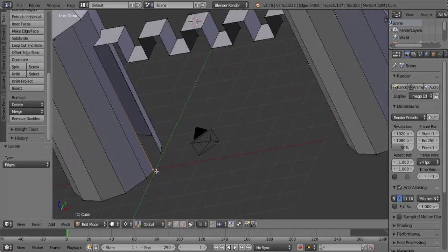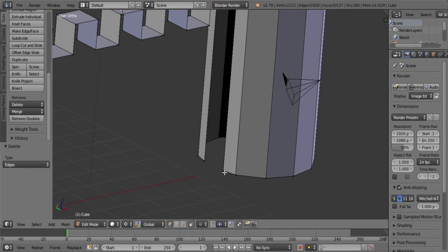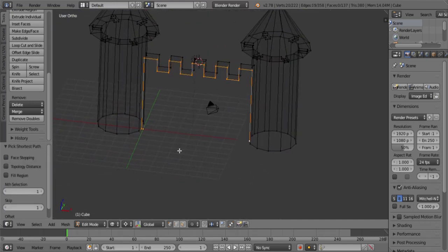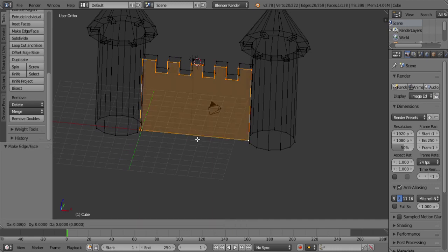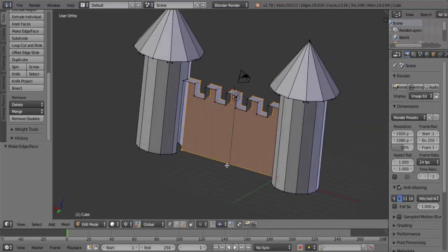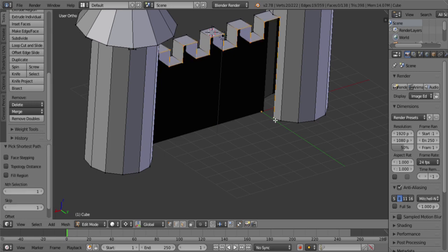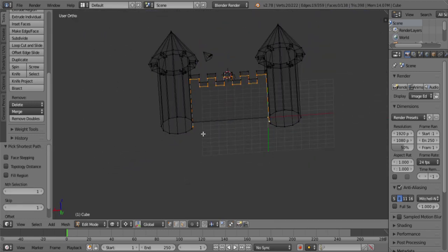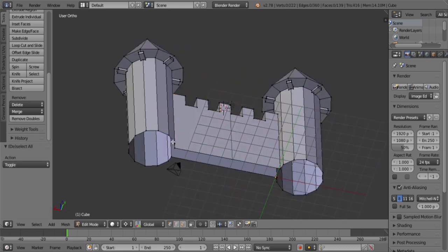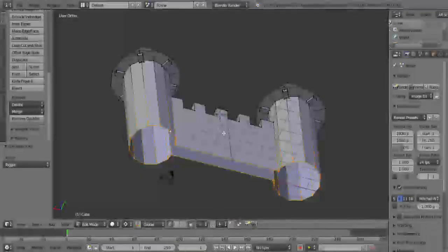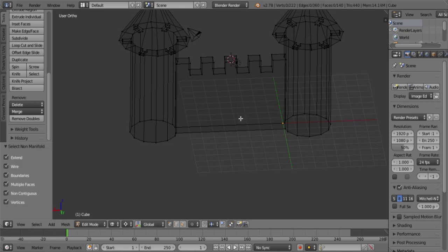But you know, I'm clicking this one and I'm keeping Control pressed and then click this one. Now it's making a complete loop from the first to the last vertex that I selected. So fix this one. Let's show it once more. I click this one, I rotate, hold down Control and click the other one. And it's selecting an entire loop from first to last vertex. Fix this one and fix this one. Normals. Let's see if there's non-manifolds. Nothing. Okay, I'm done.